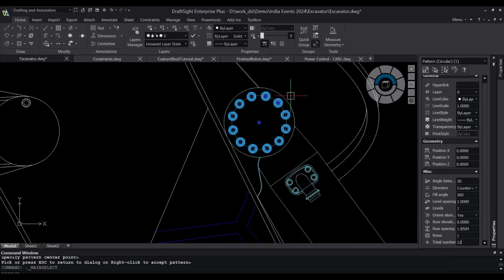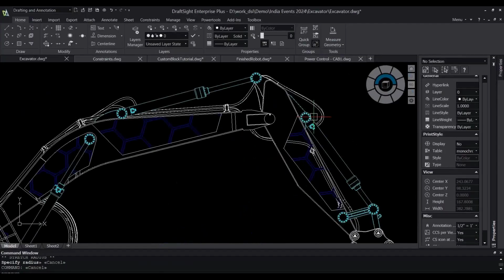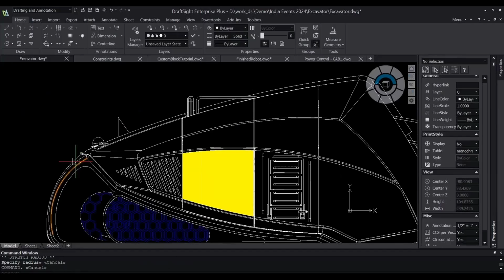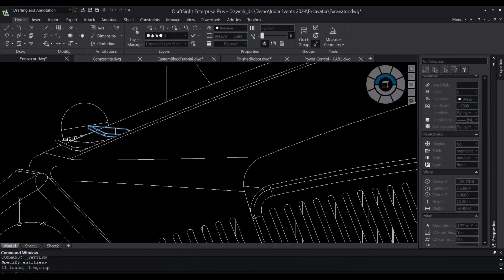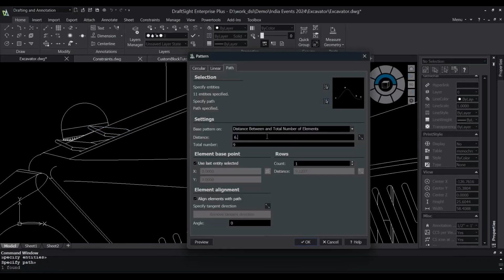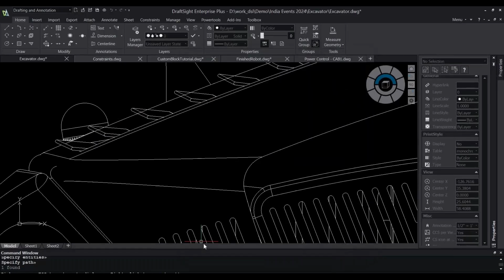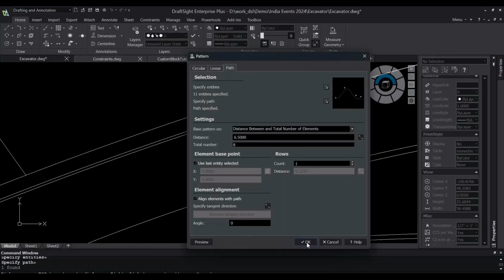Okay. So I can also manage it with the help of my drag handles for easy manipulation, and not only linear and circular patterns, there are some advanced patterns which are your part driven patterns over here. So I can simply specify those as well, check a preview of it, and if I want to update it, I can simply go back and update the counts over here.